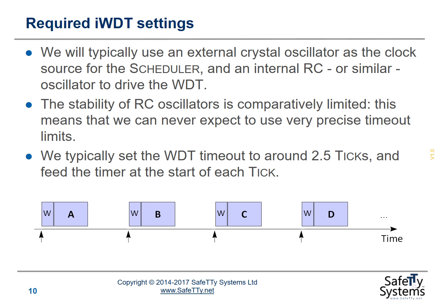The watchdog timer is there primarily to ensure that the scheduler is continuing to operate correctly. If the scheduler doesn't operate, the watchdog task won't be released, and we will pick this up within around 2 to 3 ticks.